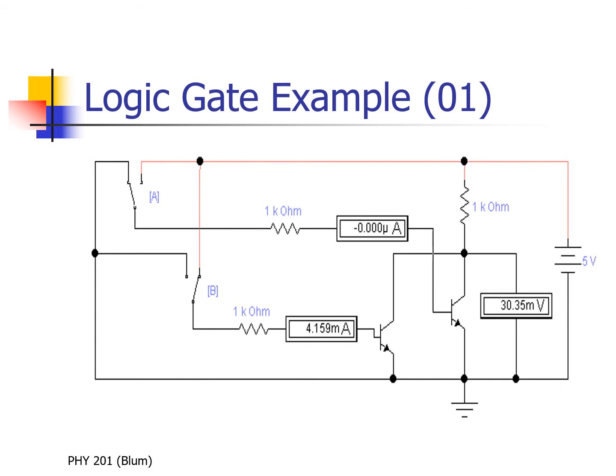Now we're going to put in a state where A is low, but B is now high. So the transistor that connects to A, the one on the right, is getting no current and is off, but the one on the left connected to B is getting a current and is on.